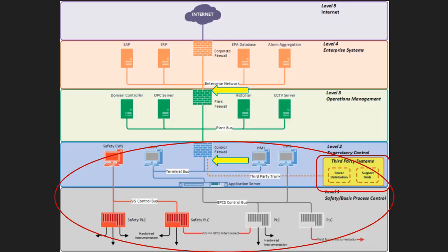Historian, which is a database for SCADA or control system data up there. You're going to have all of your flow data come up and probably land in a historian somewhere. Sometimes you may have an operations historian down here too, but closed circuit TV, physical security sometimes comes in on the same system because there's some parallels between physical security instrumentation and industrial control instrumentation.